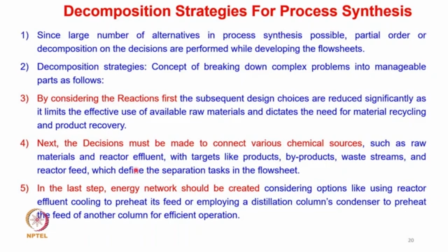And the third step is, once this preliminary flow sheet is developed, the last step, we look at the energy network, considering the options like using reactor effluent cooling to preheat its feed, or employing a distillation column's condenser to preheat the feed of another column for efficient operation.